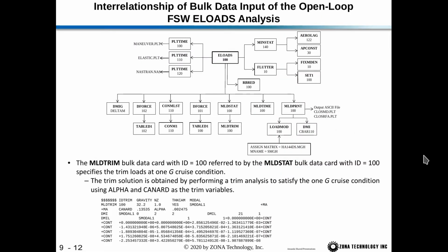This is the bulk data card interrelationship. For this test case, our ejection loads card refers to 3 plot time cards, so we can visualize the response, and then also output the Nastran force and moment cards for detailed stress analysis in Nastran after the fact.